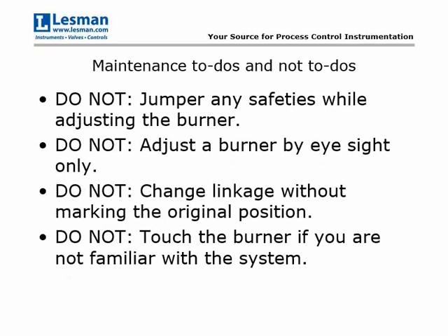You don't want to adjust the burner by eyesight only. Trained combustion technicians can tell you whether you have a rich flame or a lean flame just by sight. A lean flame, as I showed in the previous webinar, has a pale blue appearance, and a rich flame has an orange appearance, and the flame will rise up and have longer fingers that usually extend out. This is a dangerous practice, to adjust the burner by sight only.